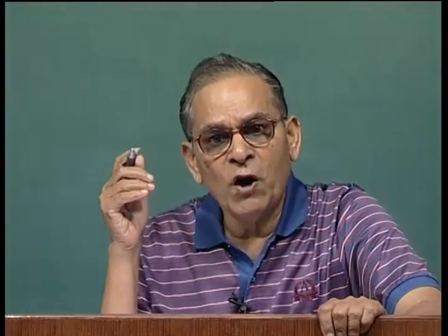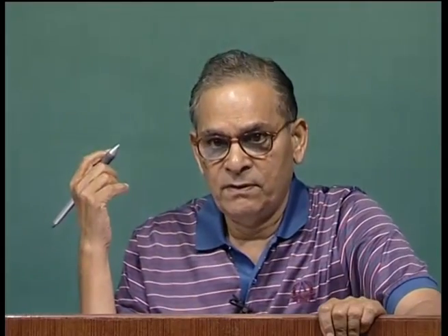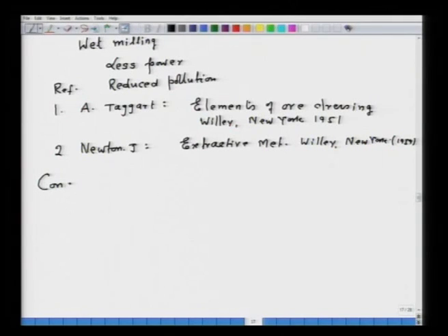milling operation. Now, once the output of the liberation technology, which is oversize, we have gotten the surety that now the mineral is liberated. Now, we want to concentrate it. So, the next are the concentration technologies. Now, as the objective is very clear, here what do we want? We want to separate the valuable mineral from the gangue mineral, that is our objective.